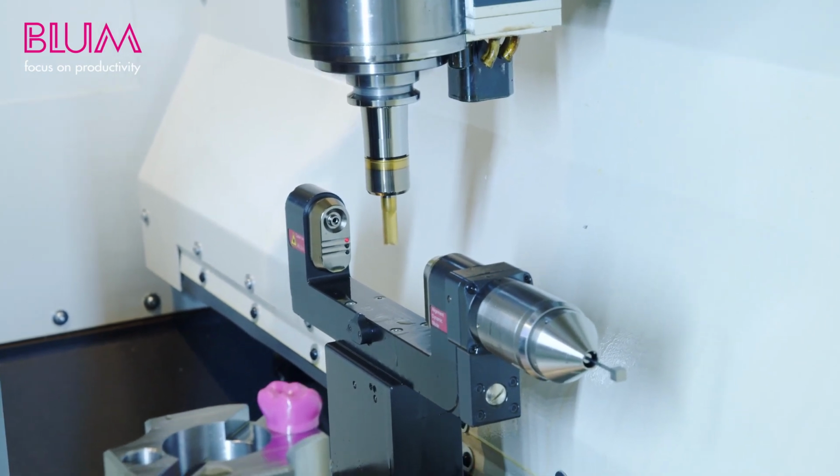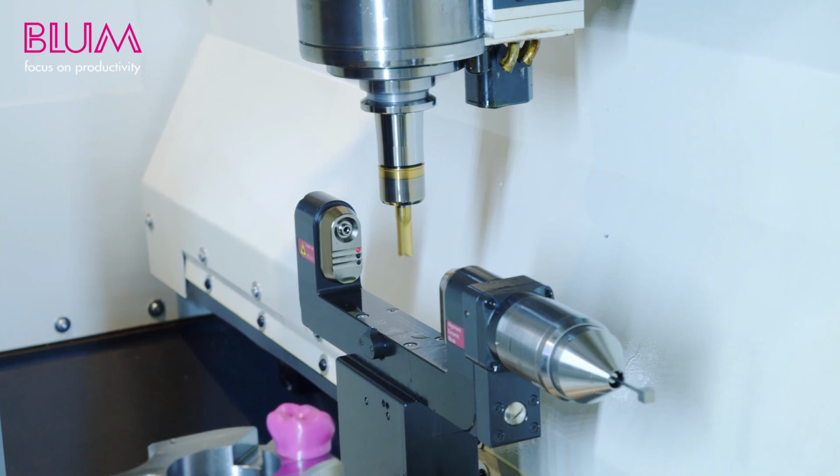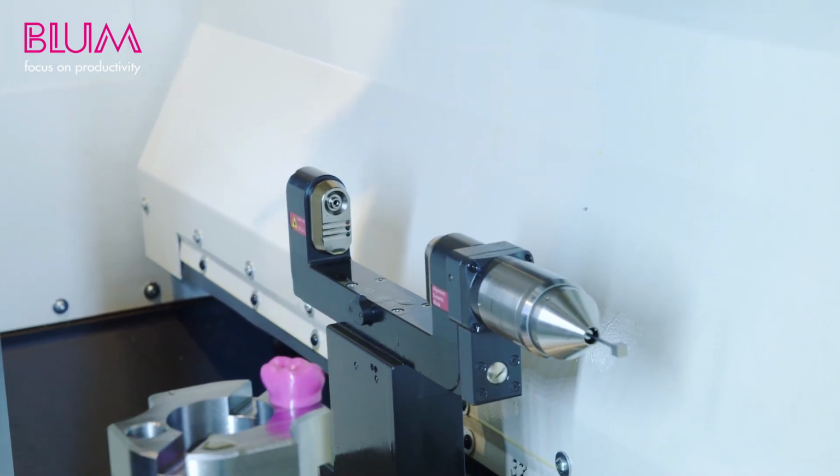The tool is positioned precisely and in a controlled manner directly in the beam. In this application, a detailed scan is then performed along the cutting edge to reliably detect even the smallest chips on this edge. And that way you have a meaningful measurement completed in no time at all.